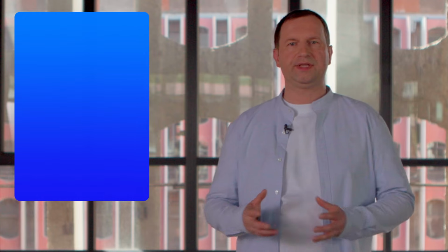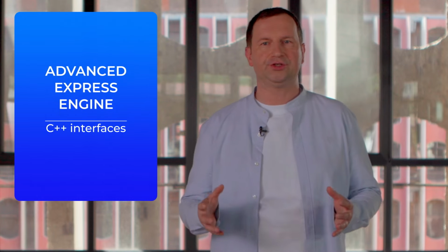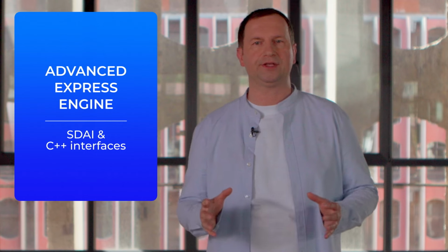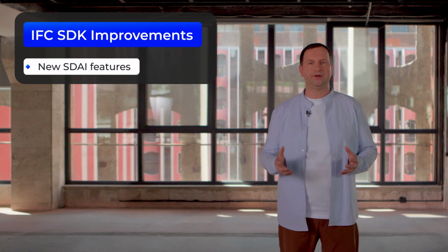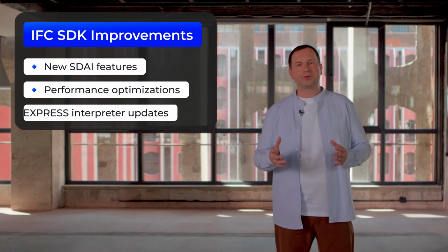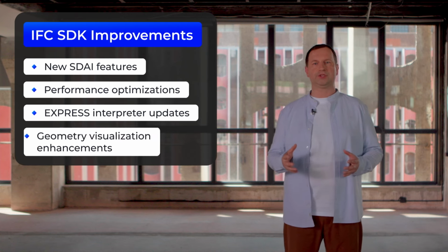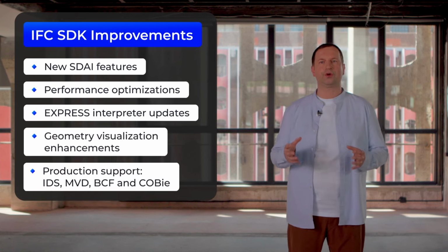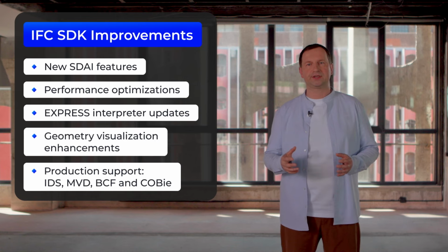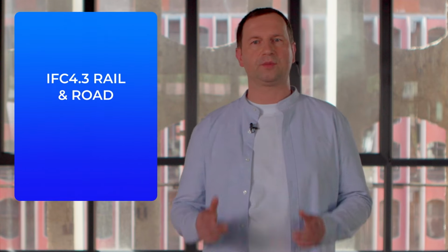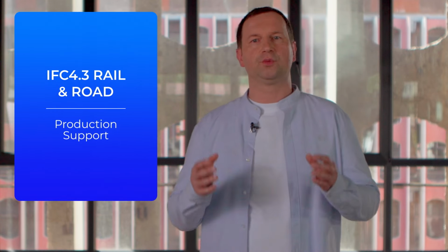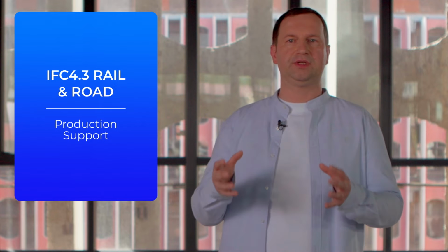ODA IFC support is based on our advanced Express engine, which includes SDAI and C++ interfaces for data access. IFC SDK is widely used by major vendors and has seen a number of major improvements during the past year. New SDAI features, performance optimization, Express interpreter updates, geometry visualization enhancement, and production support for auxiliary standards such as IDS, MVD, BCF, and COBie. The IFC 4.3 format that formalizes rail and road definitions is one of the most valuable releases within the BIM industry for the last year.